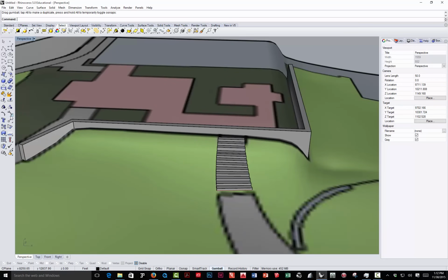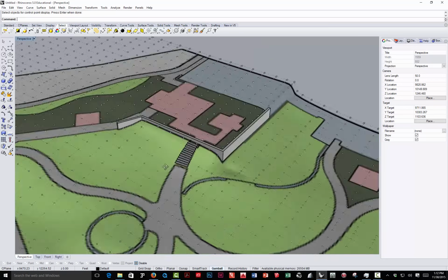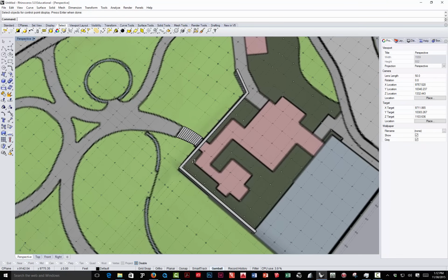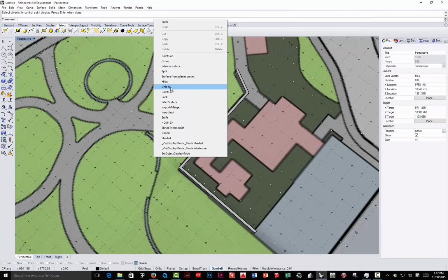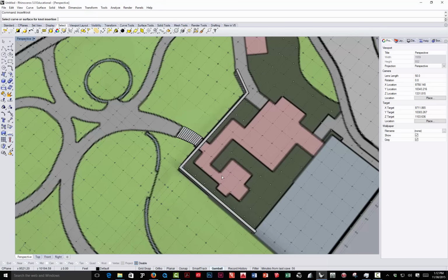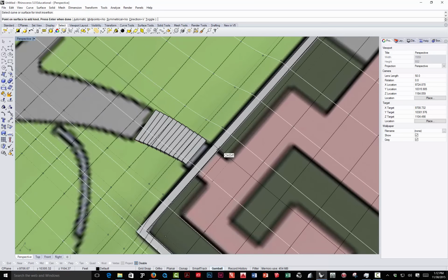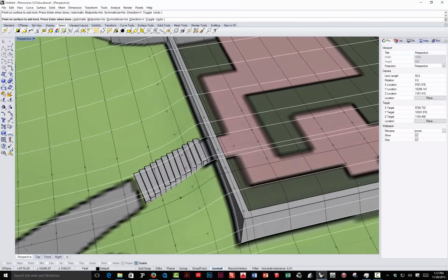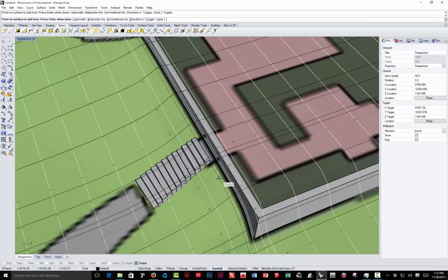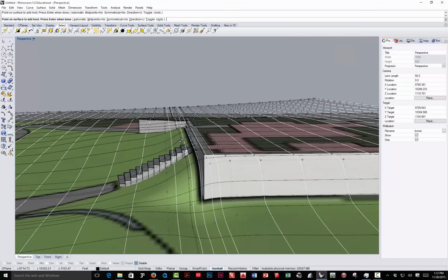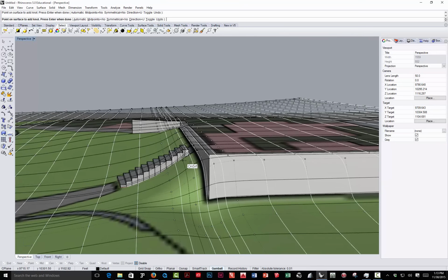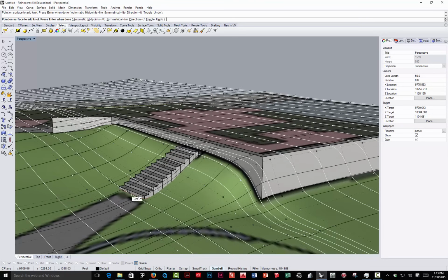And again, I'm going to turn the control points on. And I think what I'm going to do to make this a little easier as well is to go ahead and add some other knots in there. So where's my insert knot? So I'm going to come in here where the stairs come through, because those are areas that I want to control, all right? Then I'm going to toggle, and I'm going to bring it right along the front of the steps. That might be enough. And I'm going to come down here, that corner, kind of this corner, and enter a right click.